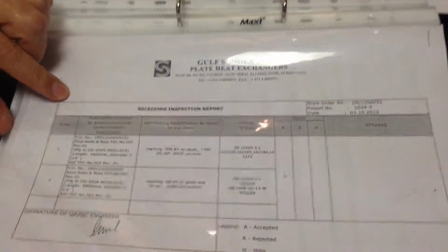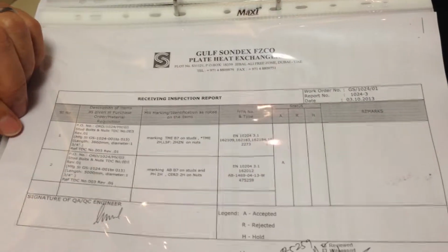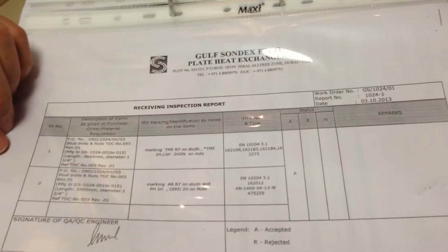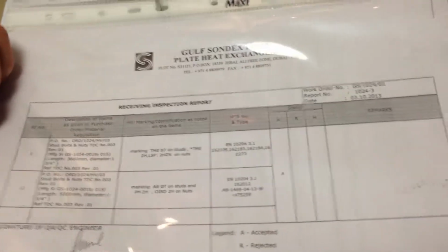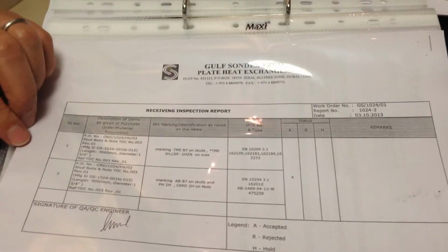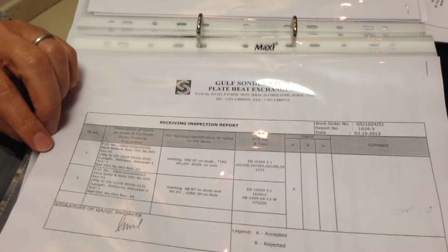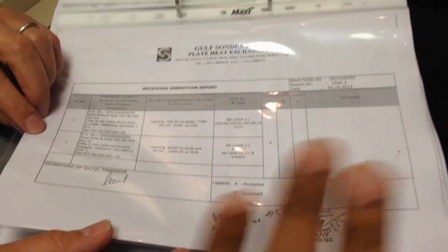So this is the first 6. The next 6 we inspected today, and the AI has inspected all of that material. He has cross-referenced the heat number to the material certificates, and he has signed on the relevant documents. And this one is for the stud bolts and nuts, for the tie rods we are using. We have 2 different types of tie rod, one is 5 meter and one is 3.6 meter. So this certificate for all the units I have kept over here for the 15 units. Nuts and some materials we still got yesterday, that we will inspect later. But for the 6 units, everything is complete here.